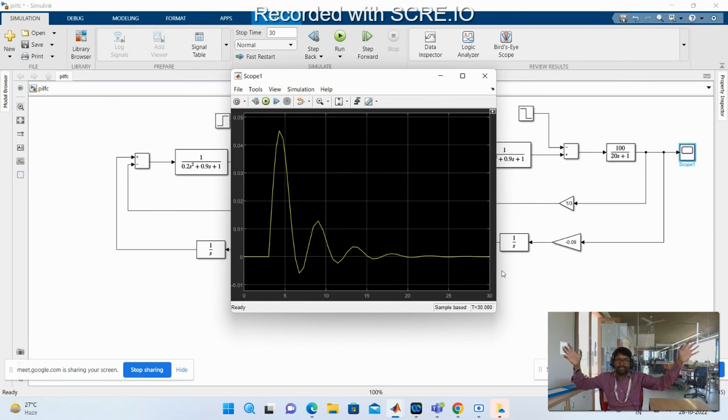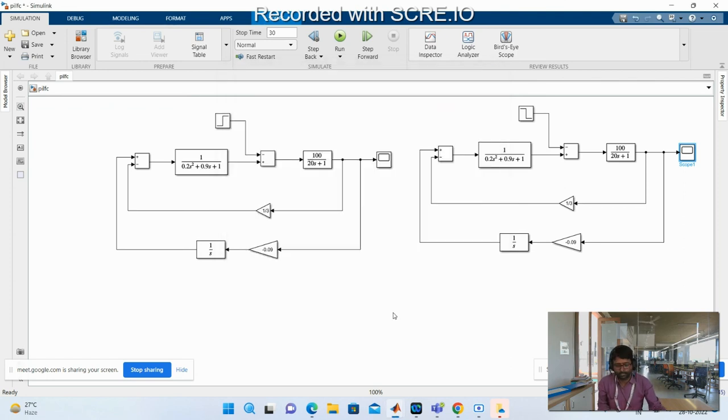Physically, you understand. Your PI controller will read the frequency deviation and give the signal to the speed changer. Your speed changer position will be updated, and your valve will either open or close. This will be a continuous process until delta f equals 0. That's the physical aspect, and we are also visualizing it here in the simulation. Mathematically, I have to do the proof, and I will do it on Monday, in the next class. Okay, Naman? Thank you for your active participation, and I will share all these diagrams with you.